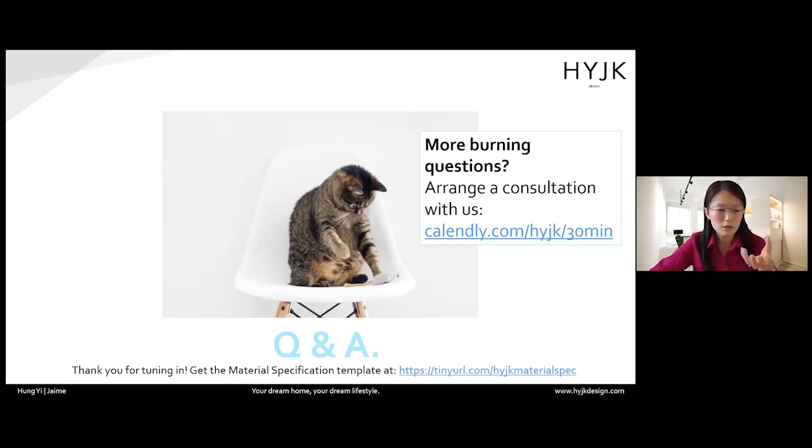And if you use something that's a bit too hard, like one of those sponges that's very, very rough, and you try to scrape it off, you're going to scratch your solid surface top. So it's not advisable. I would say it's really not so easy to fix an issue with the solid surface top. From what I understand, the experts use some chemical and do a bit of grinding, but to a certain extent only. It's not 100%.